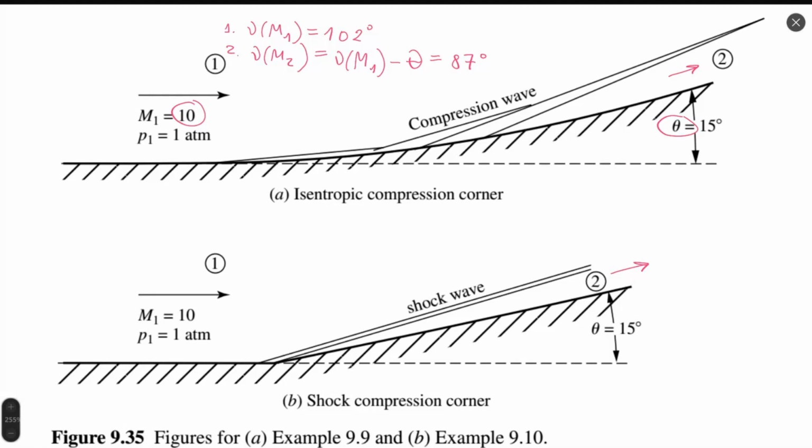When I have the Prandtl-Meyer function, I will calculate the Mach number at the exit. I will look where is my 87 degrees in appendix C. I will take the approximate closest value. It's Mach 6.3. Okay, I'm finished working with appendix C, and I can calculate pressure.